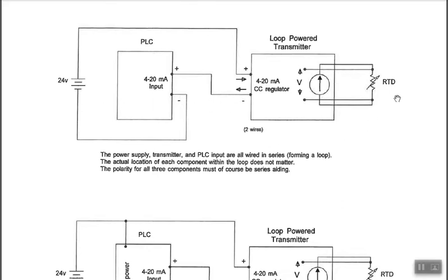So remember, way over here, you've got temperature causing a varying temperature, causing varying resistance, causing varying voltage, which the microprocessor converts and scales to a varying current. That varying current is sent to the PLC to then have an idea of what the temperature is, and it'll convert it back to a number for your PLC program. So here is the milliamp current that represents the temperature.